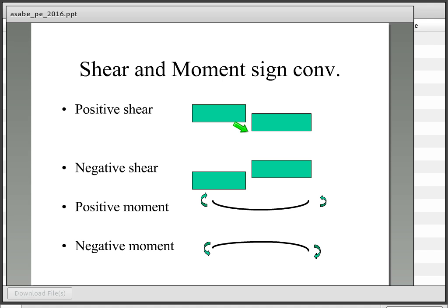And so if I were standing on this section here, looking down at this face once it's been sawed in half, I'm going to be seeing a shear vector pointing vertically. And it's going to be equal to that vertical load over here, because sum of forces in the y direction for this little sawed off segment has got to be 0.